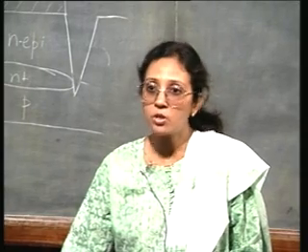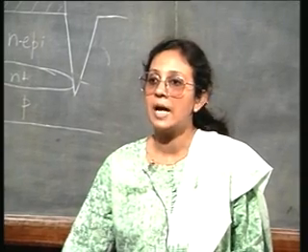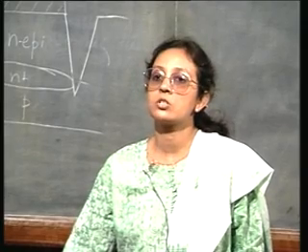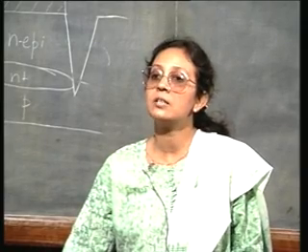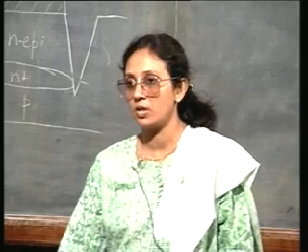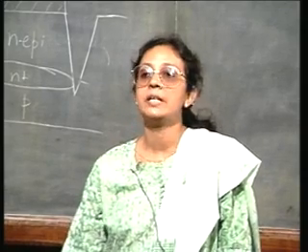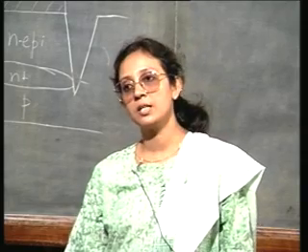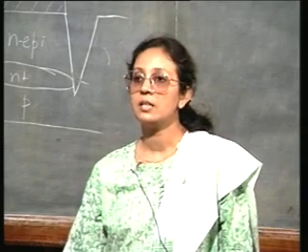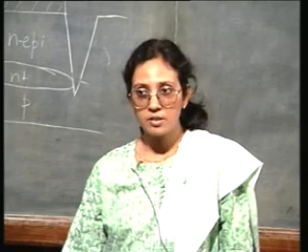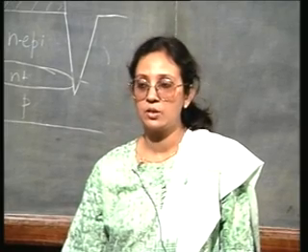We do not want oxidation to proceed in the active region, we want oxidation to proceed in only the region surrounding the active transistor. And let me recall to you a very interesting property of silicon nitride, which makes it a very interesting material in VLSI technology.